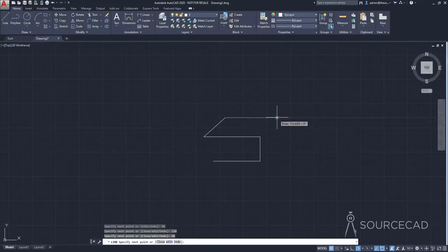So you can keep on making your lines by entering the proper distances, and it will just make your line that way. Also in this case, if you want to add angle values, then that also you can do pretty easily. So in this case, let's just make another line of length 100. So I'm going to go to 100 and enter. Now this length is again 100.